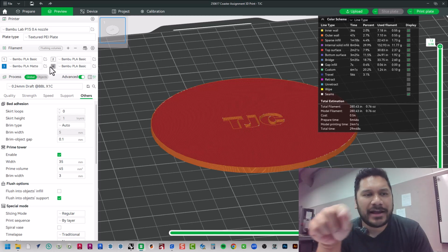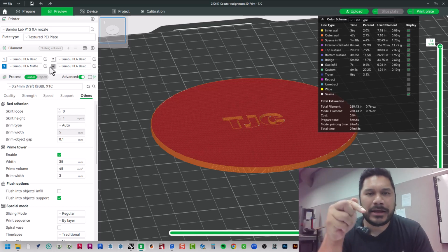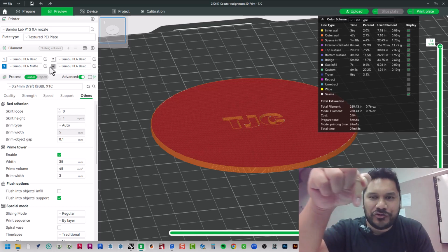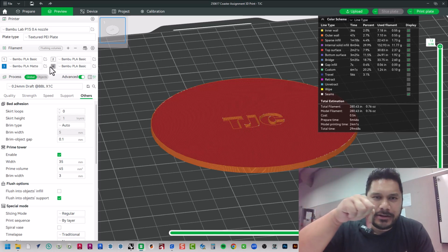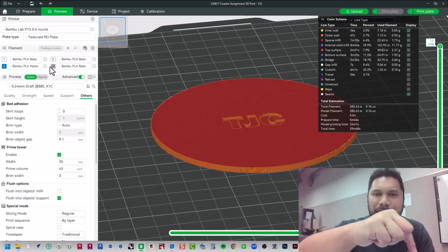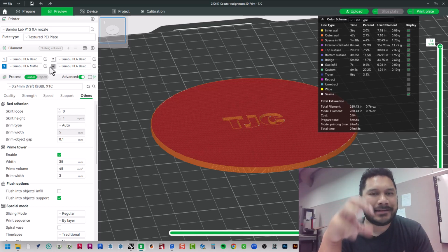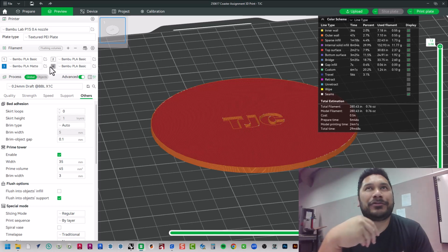The extruder heats it up, and it basically is dripping warm or hot plastic in a very precise pattern, which is dictated by something called G code. And that's what our slicing does: we're not only slicing our 3D model, but as it slices it, it's creating a conversation with the 3D printer as to what and where that extruder needs to be.